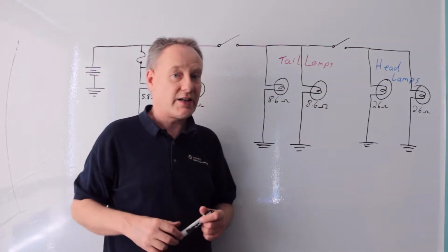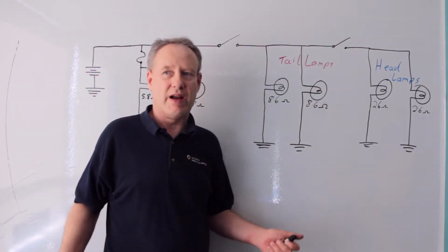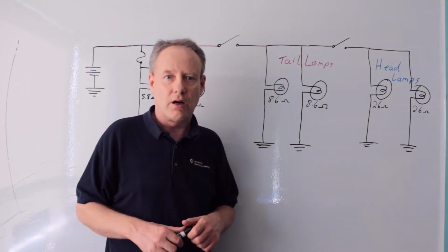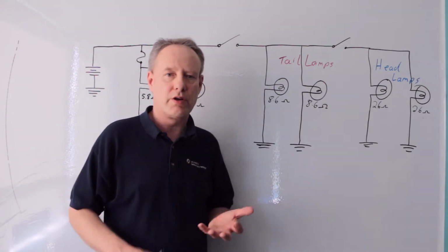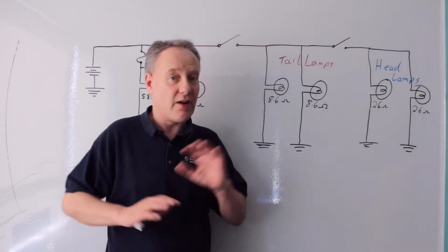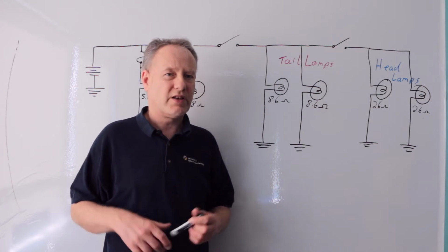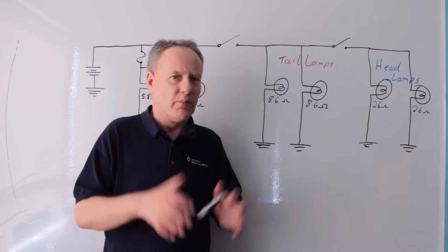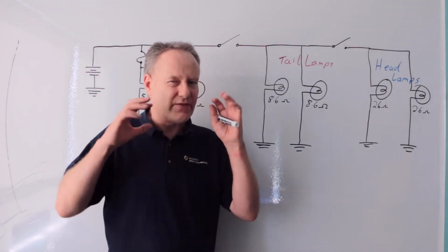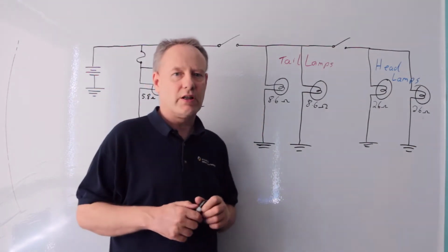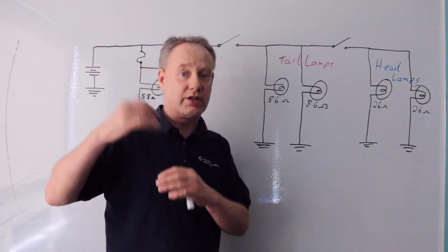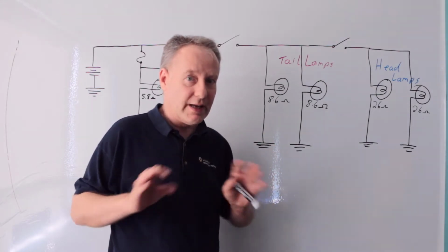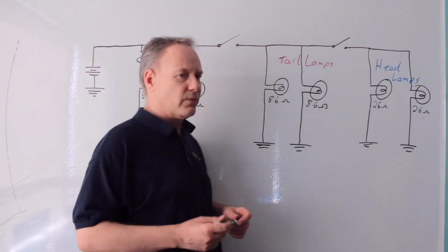all the way along. So actually, all loads, except for maybe a radio circuit, your computer, and some other fancy things in your car, are all 12 volts. The fan, all the motors, the power seat, everything in your car is working on 12 volts. Let's say an old car that runs on 6, or maybe an older diesel that runs on 24. There are different voltages for different specialized vehicles. Forklifts run on high voltage, like 48 or even higher. But let's just talk about a normal vehicle that you get in and drive and it's got brake lights.